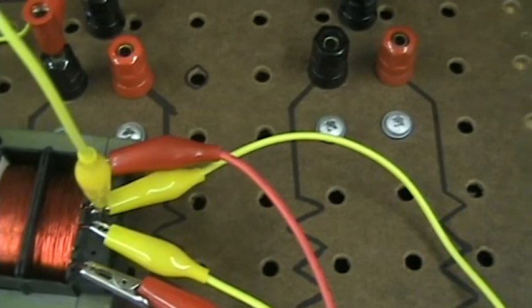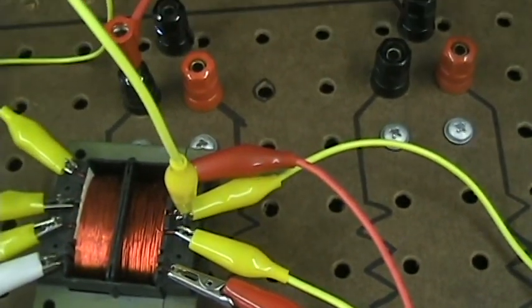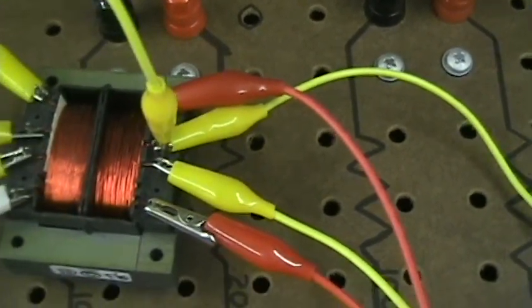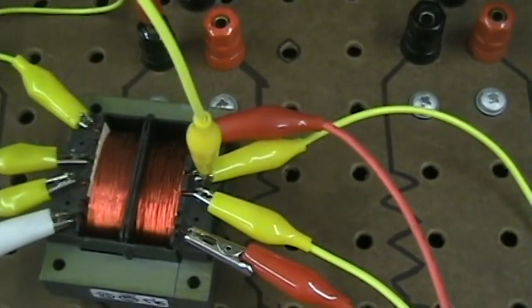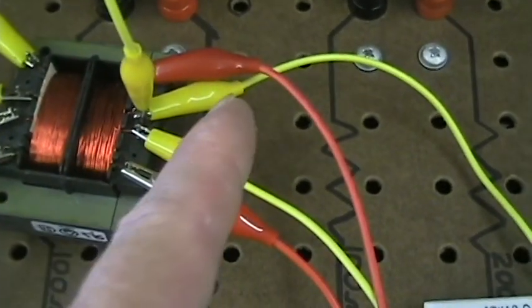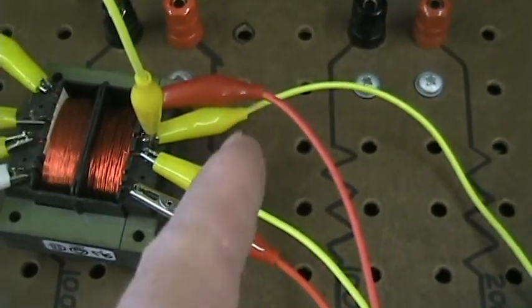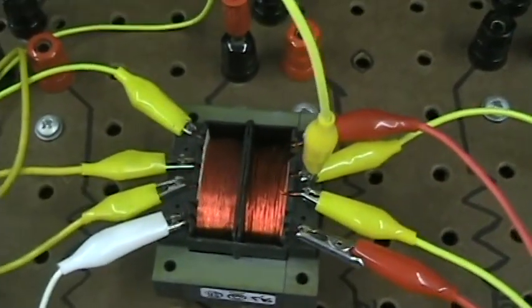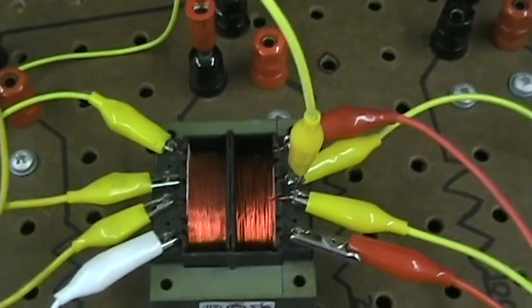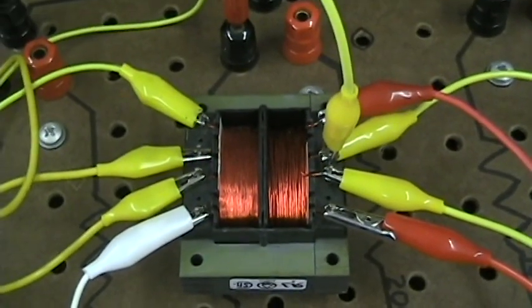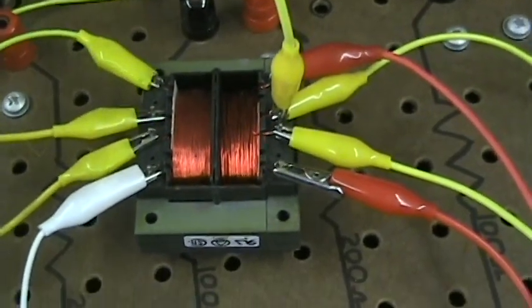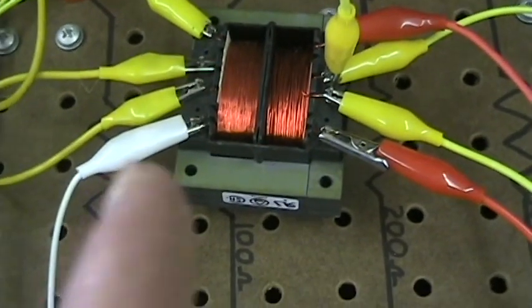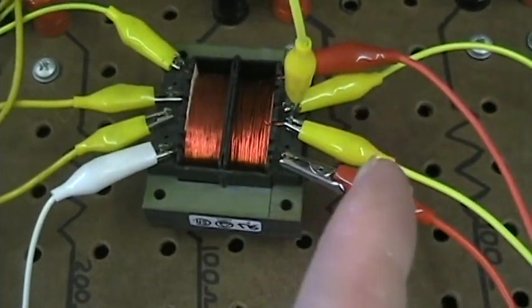If we tried to do that in the AC case, the 115 volts would only use one winding. In this case, we get two low voltage circuits and one high voltage circuit. So that's the advantageous way to use this grounded transformer. This only works because the transformer is isolated on its outputs.